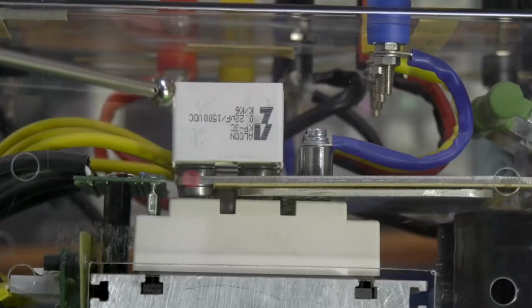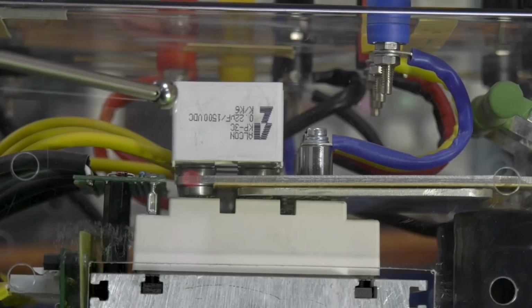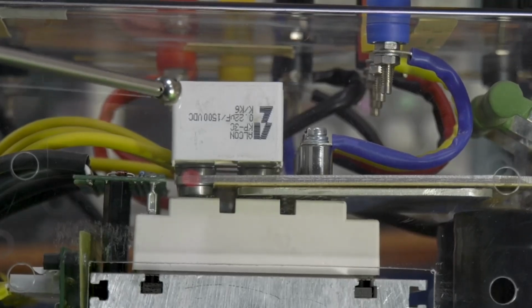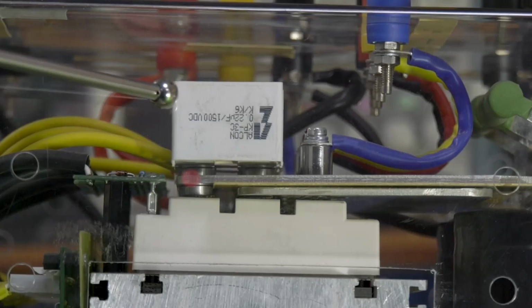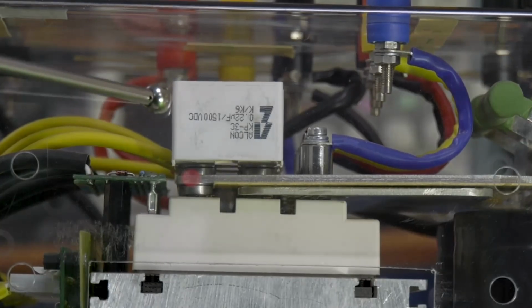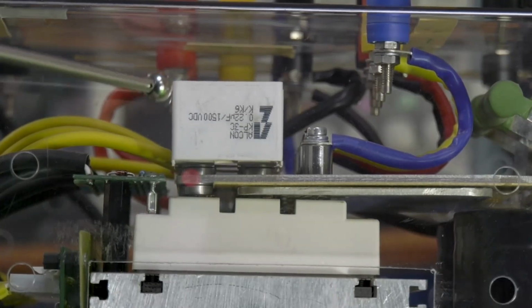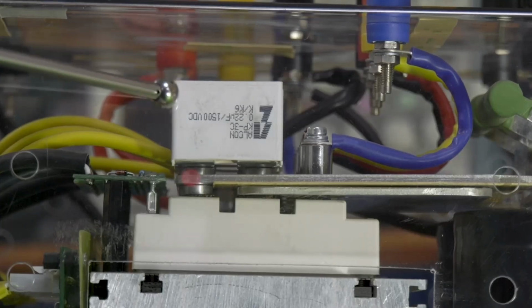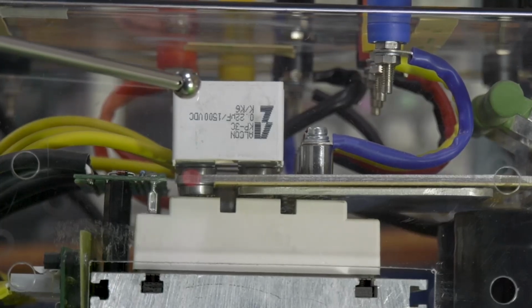Within the stack, forced air cooling through a fan is also provided for carrying out fast cooling. Also, in the inverter section, one can notice that each IGBT module is provided with snubber capacitors, which are connected in parallel to provide protection against the high dv/dt.